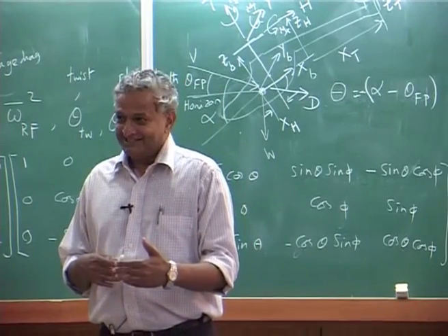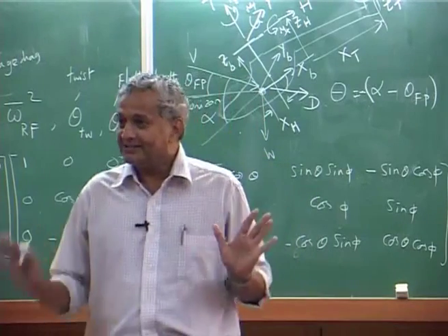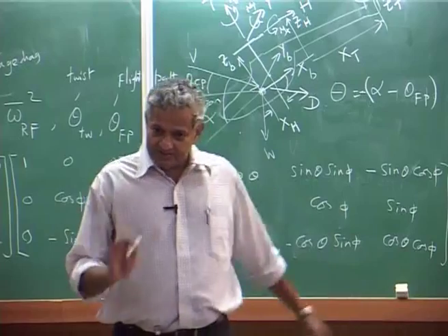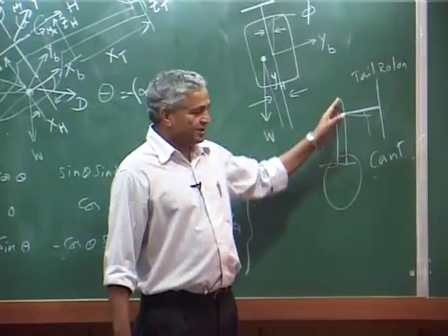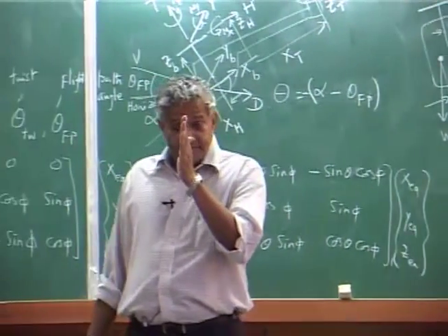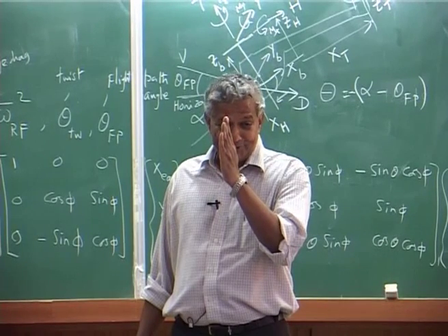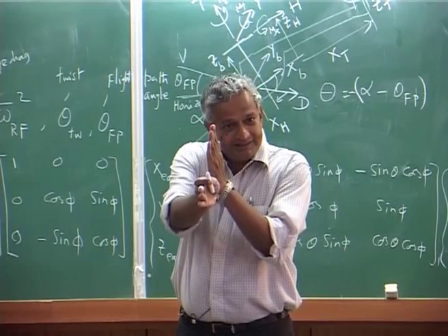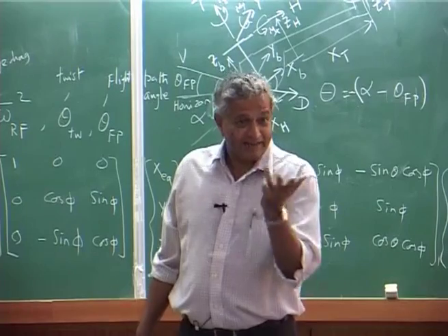Engine may have power, but pilot cannot fly, it will not be in equilibrium. So, that is why all the fixed surfaces they introduce. Now, you may say why they have to have a vertical fin, because you asked about the vertical fin. What happens is that the vertical fin will not be at 0 degrees, it is slightly given 1 or 2 degrees, to the longitudinal line of the helicopter, that is at an angle of attack.